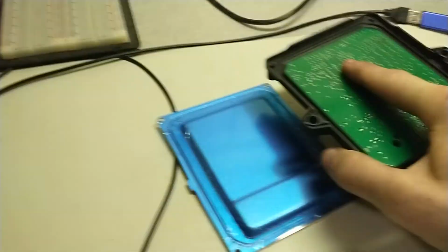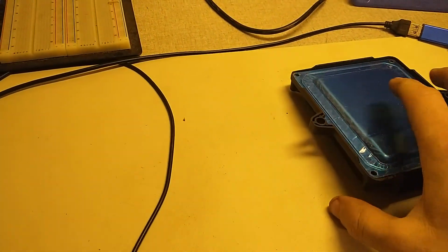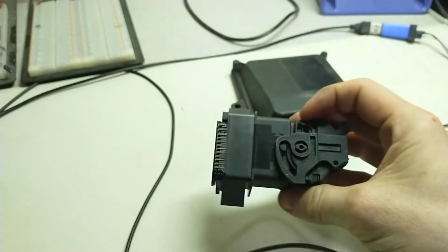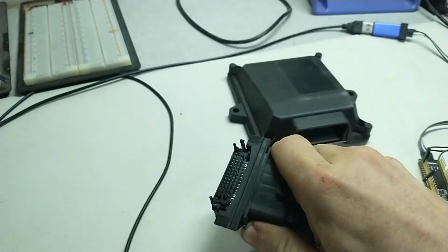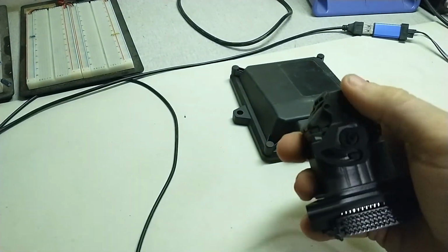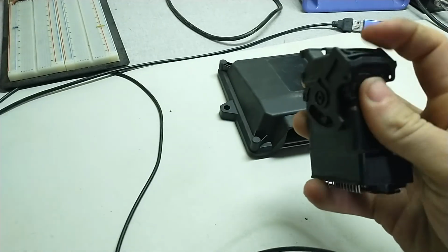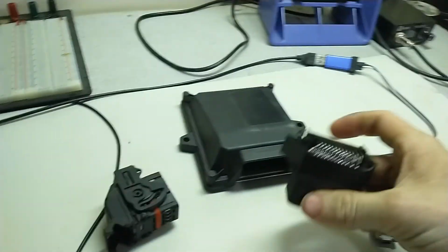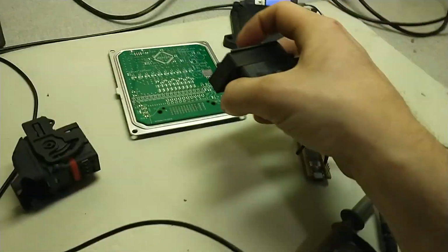So that footprint is all good, and then this metal backplate here, and then there's a connector that comes with this. So there's a 50-pin connector, and I got the footprint of this right. I actually adjusted it after I received this, since I was able to figure out that it was a little too snug. It was difficult to get this connector in there, but I've got the footprint updated, so then the next revision, this will be easy to put in here.